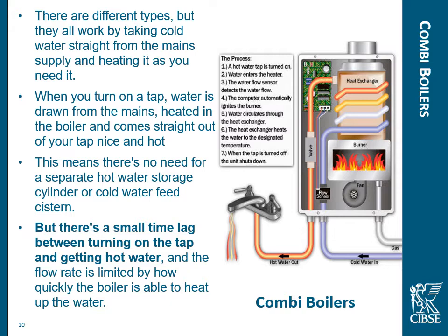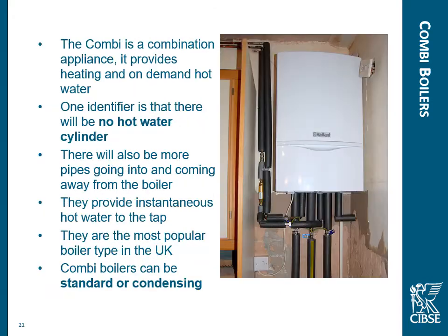So this essentially is an instantaneous hot water heater. The water goes into the boiler, it's instantly heated up in the boiler, the fan comes on, that gets rid of the flue gases, and water arrives at the tap and comes out hot after a few seconds of the boiler starting there. A good thing about that is it only heats up the amount of water we need to use at that time. The bad thing is it can't cope with 2 or 3 things at the same time. So if 2 people are using the water, the system can't cope with that.